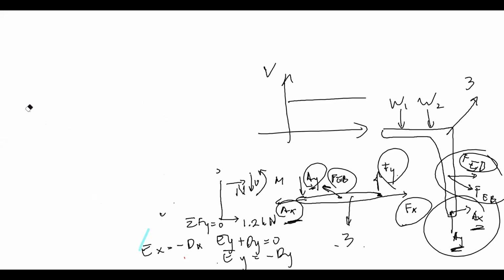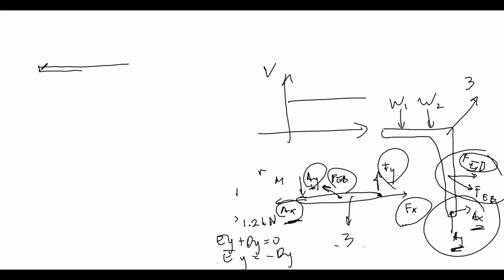Whenever you have a cut like that, right? Let me draw it again. So just now the problem is like this, right? And in the middle there is a moment clockwise. Here, 240 Newton meter, right? Then we have AY, AX, and then we have BY. My assumption is you already know the value of AX, AY, and BY.